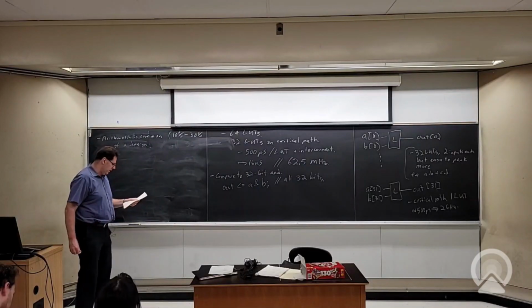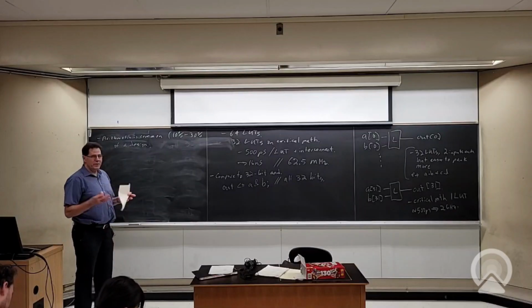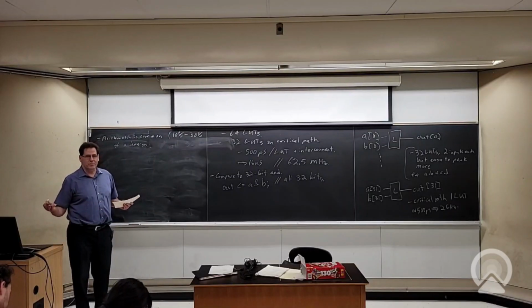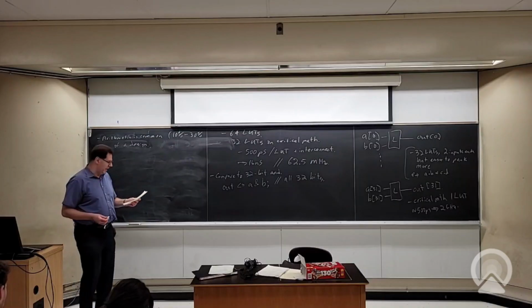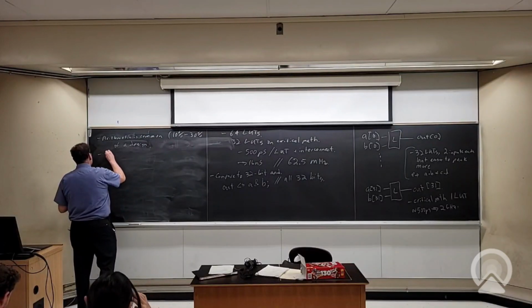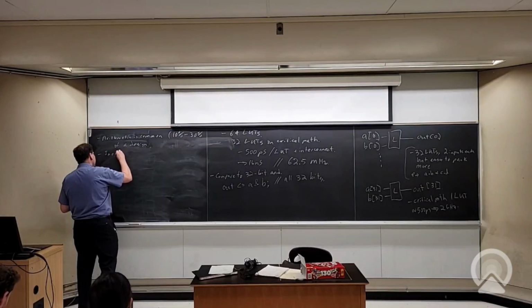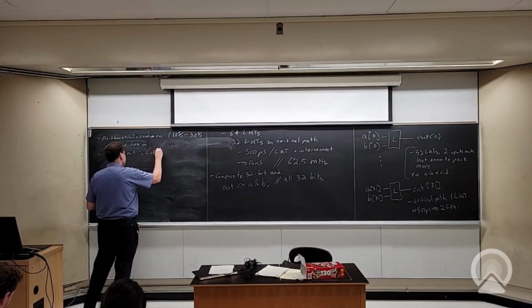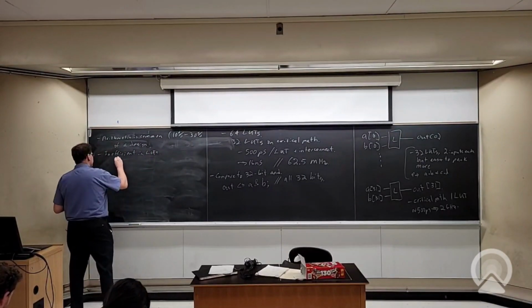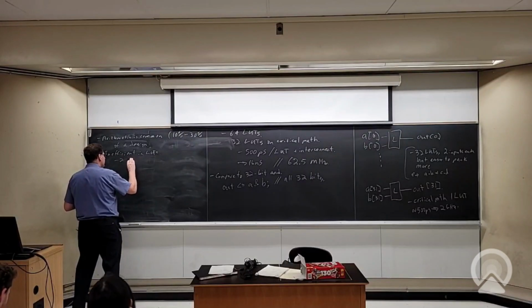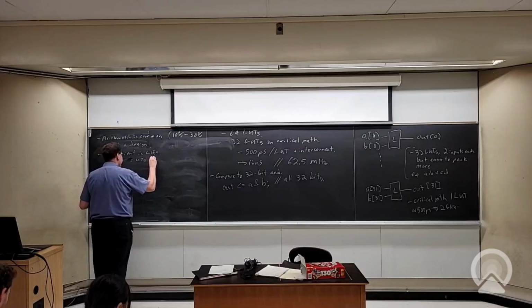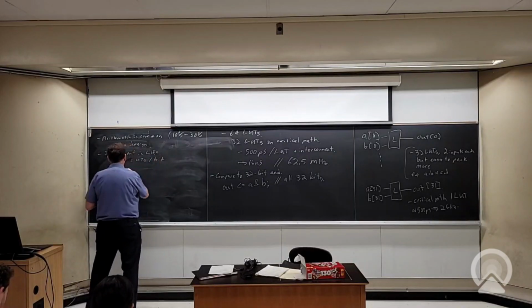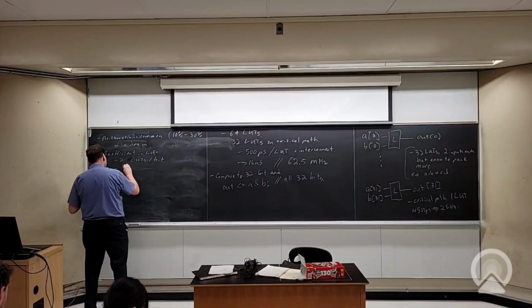So it's a lot. If this wasn't very common, then we just wouldn't care about it. There's lots of stuff we do that's not efficient, but doesn't matter if it's not done much. But this is very common. Okay, so it's inefficient in LUTs. Right, so it's 2 bits or 2 LUTs per bit, so it's area inefficient. And even worse, it's got a long critical path.